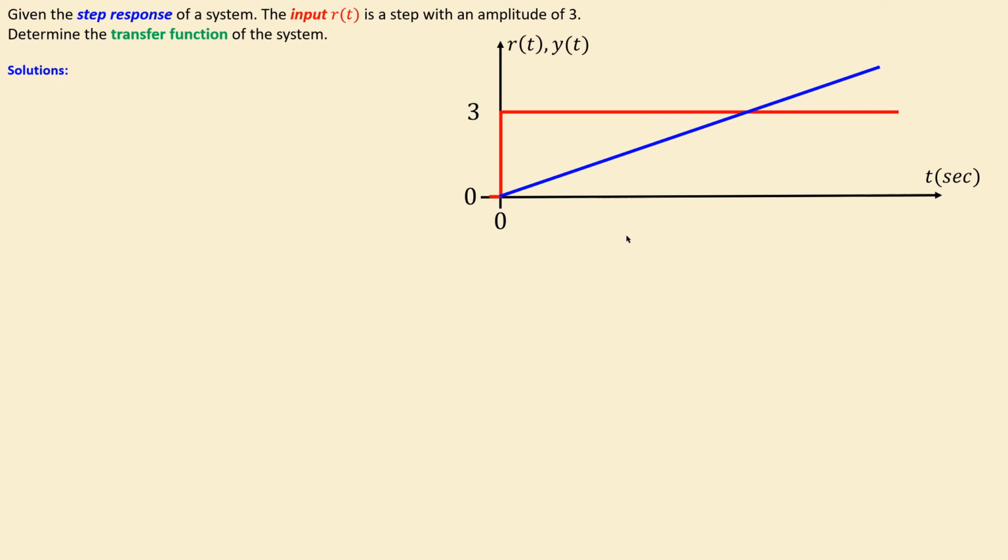So the solution step by step, let's look at the observation from the plot. Of course the output is the most important part here. First, with the output, we can see that it is linearly increasing without a limit. So there is no final value here. That is, as already said, a typical pure integrator response. So this is definitely a pure integrator.